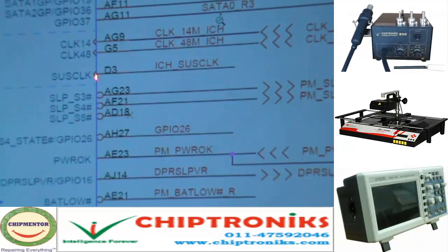We will discuss what these states are. Right now I am explaining briefly. S4 is the state when all your memory controllers get their supply. S3 is the state when all portions on your motherboard get supply. And S5 is a state after G3 mechanical off. When you press the power button in this board, the S5 state will start when the S5 enable signal comes from the IO chip.